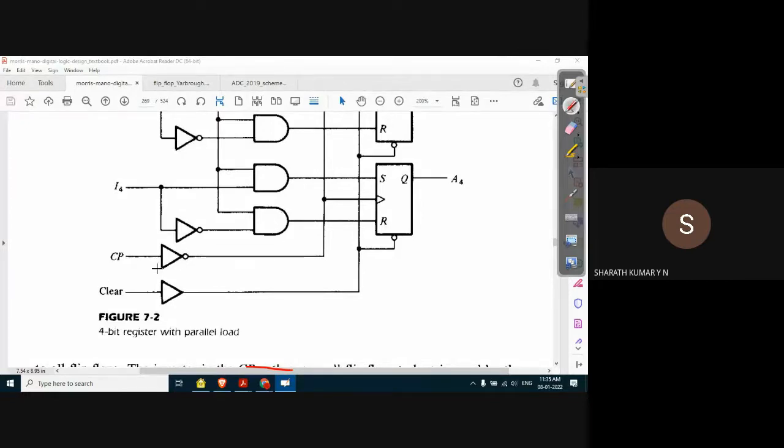One is the clock pulse. Obviously, this is a normal sequential circuit with synchronization signals. The clock pulse goes through a NOT gate, so it is complemented and applied. Even if it's complemented, we get back the complemented signal, so the flip flop will trigger at the positive edge of the clock pulse. That's simple.